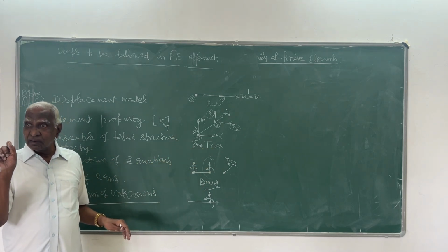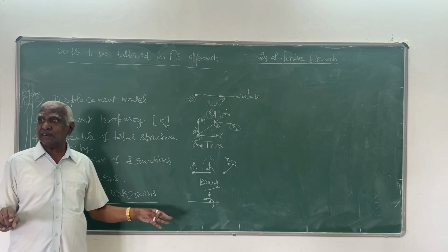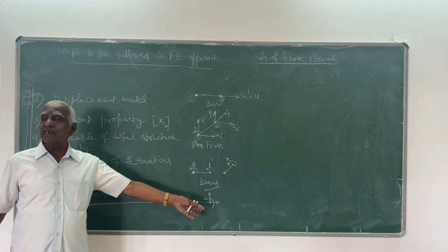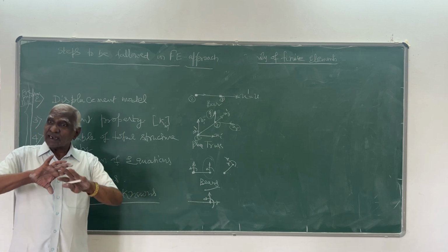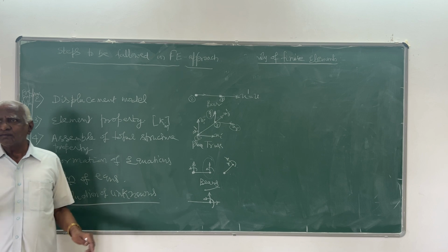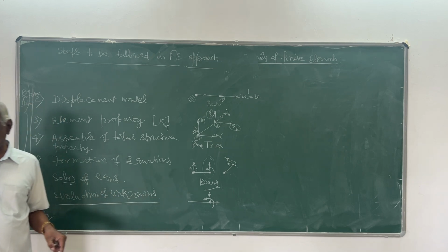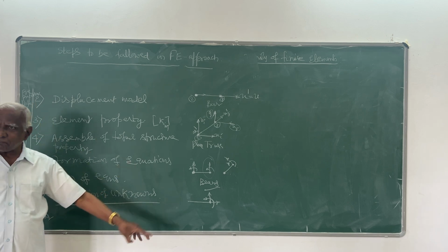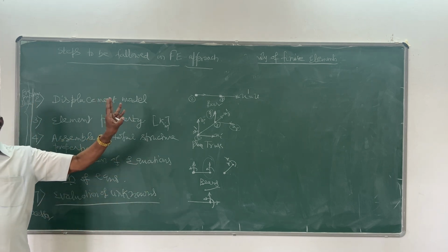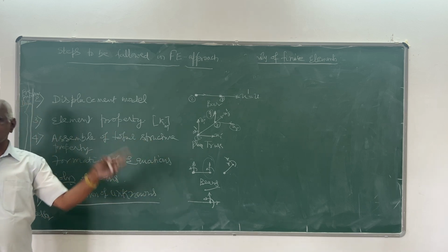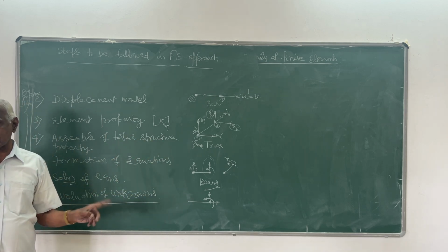It will have restraints, especially at the boundary. So you have to remove all those restraints from the general degrees of freedom. After removing, whatever is left out, that we call the kinematic indeterminacy. But degrees of freedom is the general total displacements which are possible in the structure, irrespective of restraints.